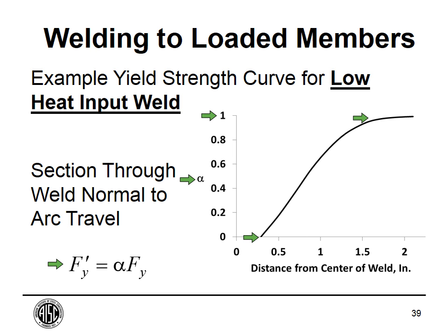Now, one thing I want to point out on these last 2, don't use this for anything specific. This is just an example that I made with certain welding parameters. In fact, I think it was made with heat input of 25 kilojoules per inch. And a lot of the flux core processes, you know, can get to around 85, I believe, or 90 even, close to 90 kilojoules per inch, which would make this move out in this direction. So it would make our area affected by the heat larger.